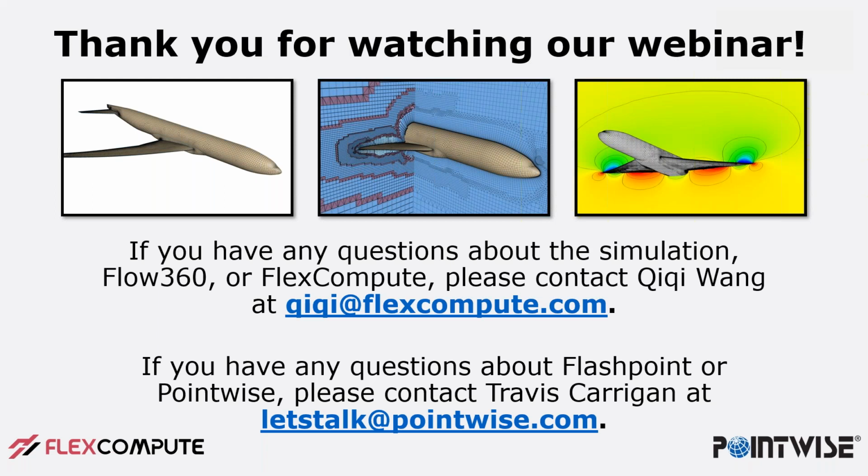Is there adaptive mesh refinement? So Pointwise does include solver independent mesh adaptation. So long as a solver can write a point cloud data file, which is basically just a collection of XYZs in a desired cell size, we can bring that into Pointwise and adapt both the surface mesh and the volume mesh, and then kick out a new mesh for the solver to interpolate and keep running. There's quite a few examples of this on our website. That's a good question.